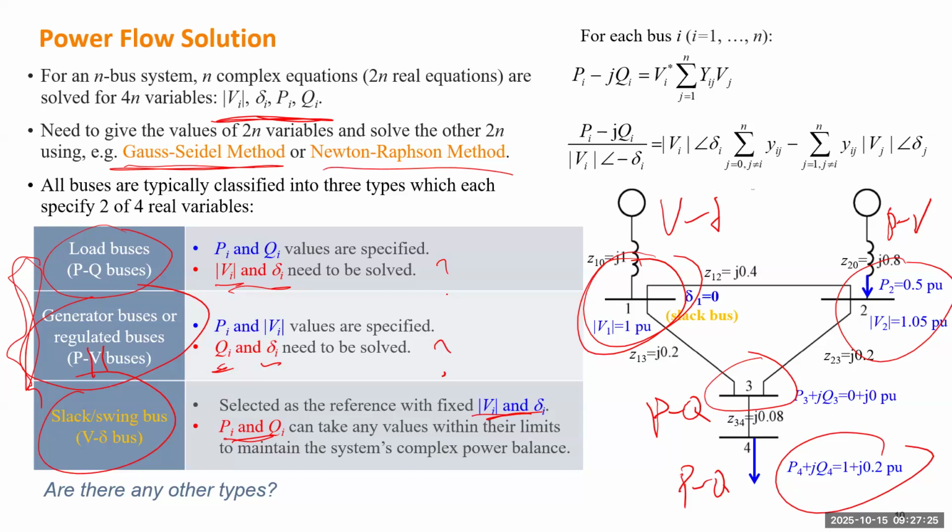Angle may utilize some control system which is called a phase lock loop, which can track the angle of that area and adjust the angle. That is the typical technology we utilize to construct some angle or phasing for inverter-based resources, like a renewable solar farm or a wind farm connected through power electronics. Yeah, so you can definitely define any other types. But those 3 types are very important types for a conventional power system.